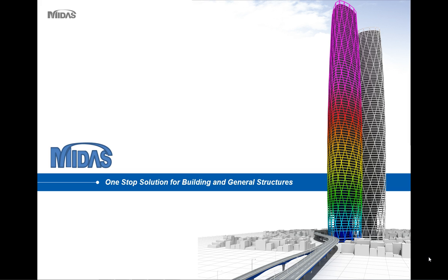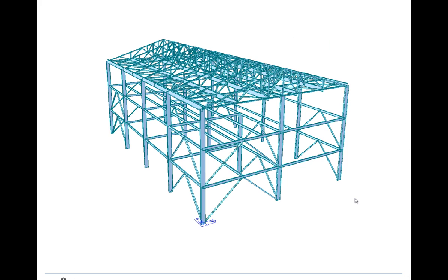Today we will see about the truss element, how to model the plant structure in the MIDAS Gen. We will even use the wizard to generate the truss elements, we can say the triangular truss element. By using these options we will see. First I will open another model, and I will tell you this is the one type of truss element we will model.